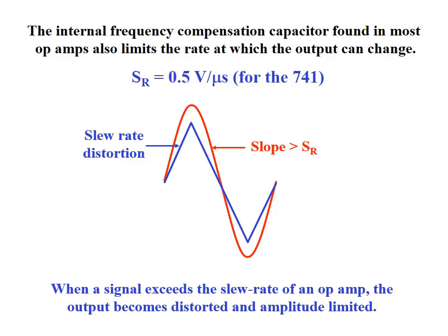The capacitor in the design is very important because it will remove the oscillation that would interfere with the desired signal. So it removes noise, but there is also a disadvantage from this capacitor. It's very important to be there, but the disadvantage is the charging time and the discharging time of this capacitor.